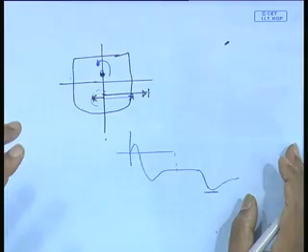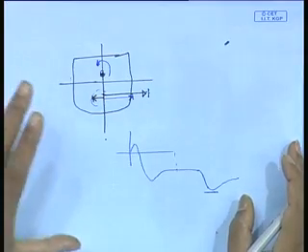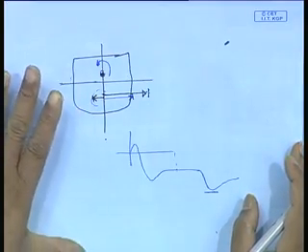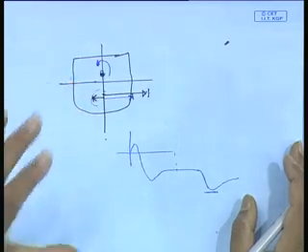So it might actually capsize. This part is always a bit dangerous. That is why when you are turning steadily, you should not bring the rudder to 0 very quickly; you must bring it very slowly.